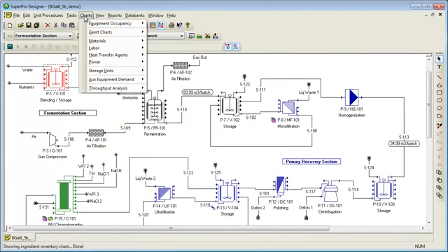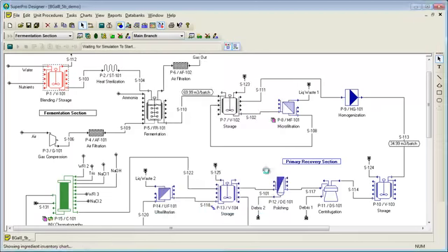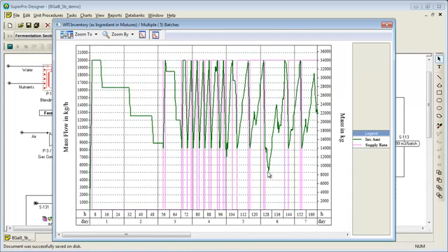In addition to resource demand charts, inventory charts can be generated for raw materials, products, and waste over the course of a campaign. Here you can see the inventory level, shown in green, within the WFI storage tank for 5 consecutive batches of our process. You can also see the supply of fresh WFI, shown in pink, flowing into the tank when the WFI still is active.